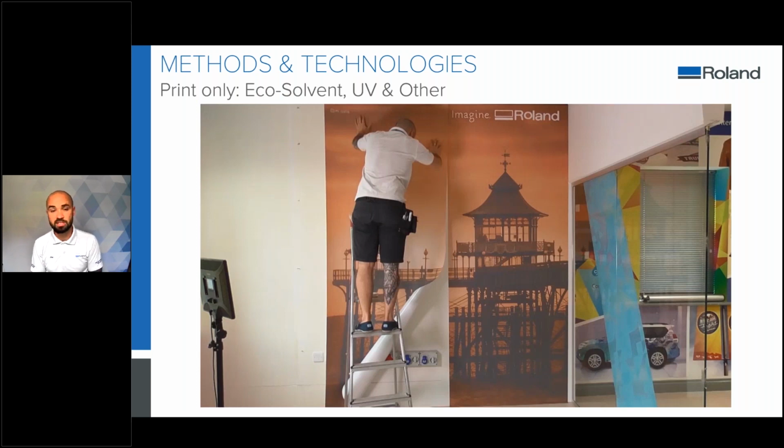Things like our polyester films and some of these ones that are used for the aqueous device, so the EJ Deco, might not move. Therefore, you might not need an overlap. Or what you can do is print the overlap, and then you can run a knife down the overlap joint and peel away the excess, giving you a perfect finish afterwards as well. So you don't have that little overlap between them. However, normally having an overlap would be the default process.